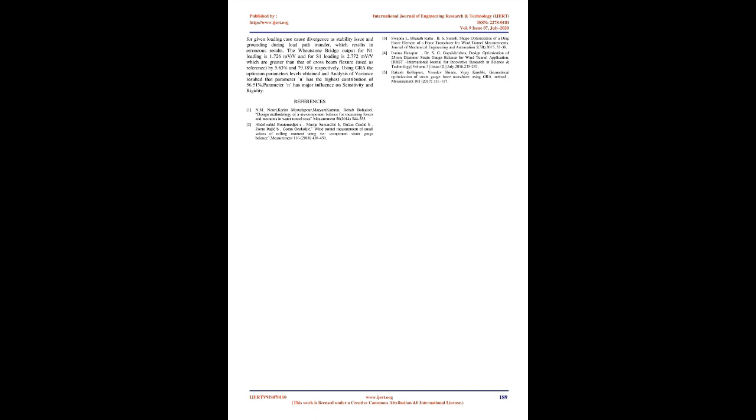F. Results comparison with cross-beam flexures. The cross-beam flexure balance with diameter of D equals 31.75 mm and length of 261.20 mm used as reference for studying performance of newly proposed flexure structure. The cross-beam flexure shown in Fig 13. The newly proposed 3 parallel rectangular beam flexures compared with cross-beam flexure of same diameter and material for sensitivity and rigidity due to normal force and side force. The deformation due to N1 and S1 load are more than that of cross-beam with increase of 4.72% and 223.36%, which is not desirable, whereas sensitivity, bridge output, for N1 and S1 load increased by 5.63% and 79.18%.